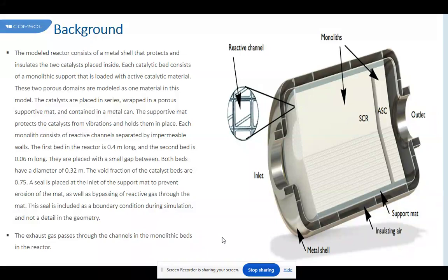The presentation is organized as follows. In the next section, we present a one-dimensional two-phase model of the monolith reactor with position-dependent transfer coefficients. Since metallic monoliths used in applications have sinusoidal channels, for which the transfer coefficients are not readily available in the literature, we present some computed new results on the asymptotic Nusselt and Sherwood numbers for sinusoidal channels of various aspect ratios.